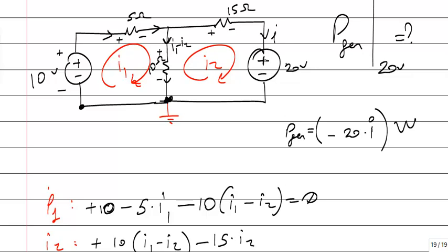Then plus to minus, again there is a voltage drop. Look, it's a voltage source, but because of my direction, if I follow the opposite direction, there will be a voltage increase. But I go in clockwise, switching is from plus to minus. There is a voltage drop. And I have returned to the same point, summation is 0.